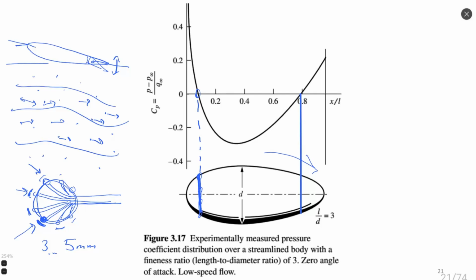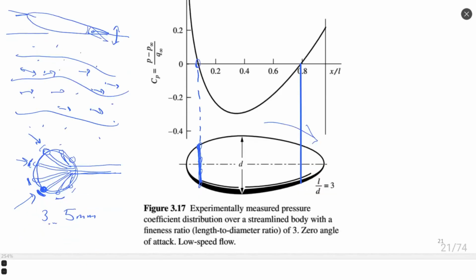But different compensation models exist, and I think we will see in future when we discuss flow around a cylinder and flow around a sphere, there are analytical solutions of the flow field which could be applied to make such kind of compensation which you are talking about, which you are asking about. So compensation is possible, and adjustment of the sensor is also possible, and it is also possible to use an advanced spherical sensor to understand the flow field without need to adjust the sensor, just measuring many points, many different directions inside the same sensor.